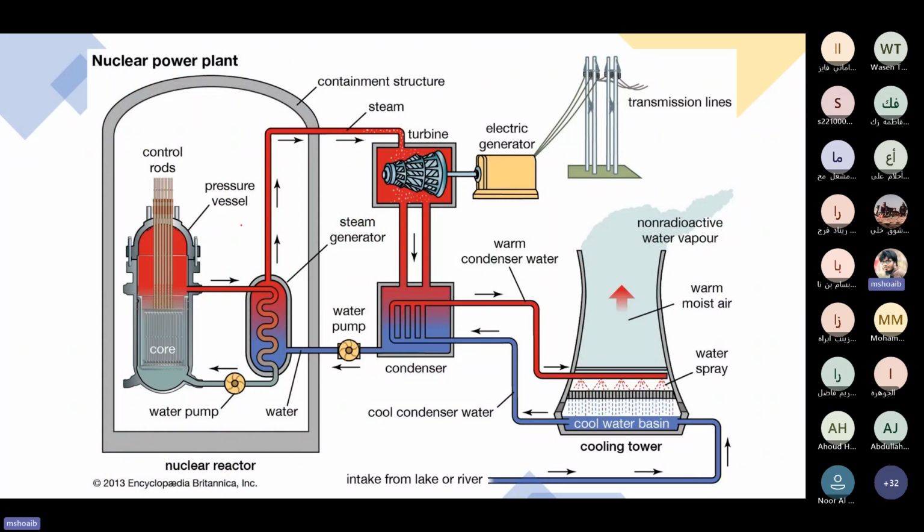As you have already understood the steam power plant or thermal power plant, this should be very clear to you. So you see, you have a nuclear reactor over here. This is the core nuclear reactor, and it has these rods. Can you see the control rods? Inside these rods you have the uranium oxide, UO2. Inside here they are bombarded by neutrons, and you control that, and it generates high heat, and that heat is passed through here.